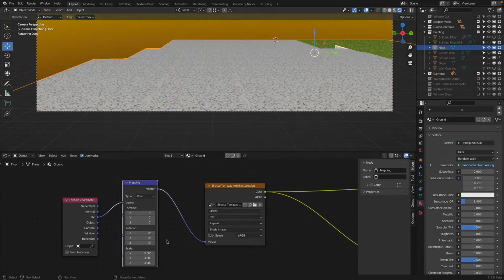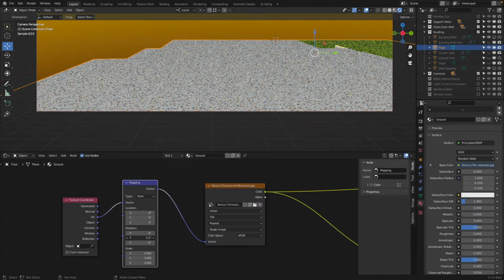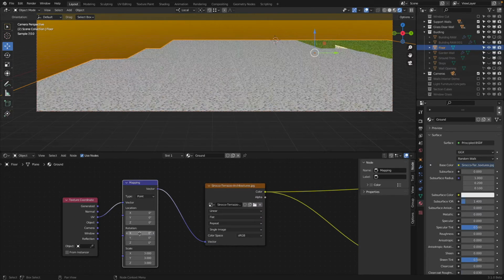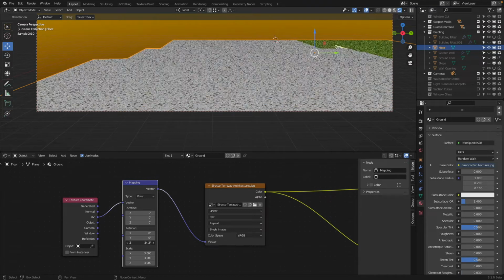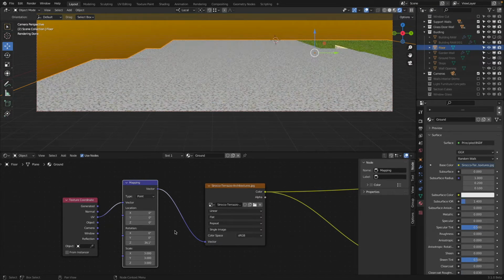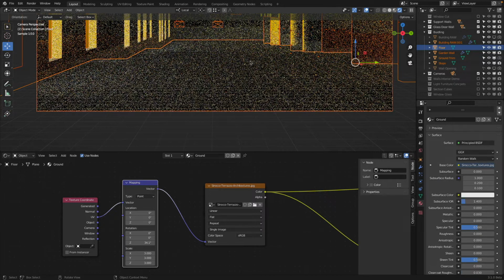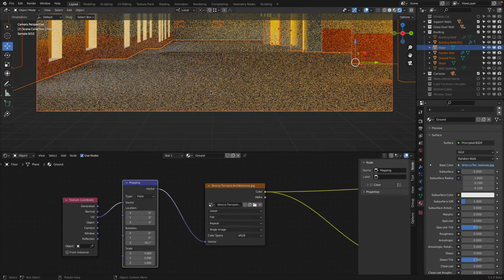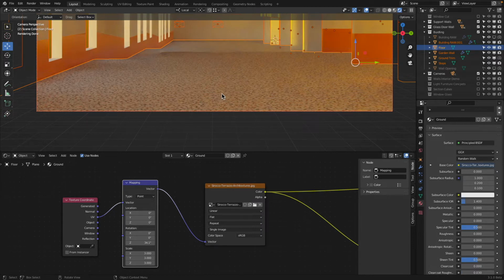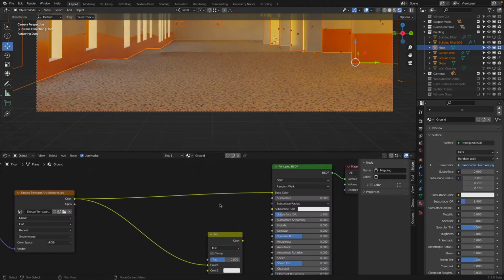We can see a repetitive line there. I'm just curious what happens when we rotate this a little bit. Oh, we can break this up a little bit. I just rotated the way the texture looks. Shift H, there we are. Now we have actually created this type of material for the ground.